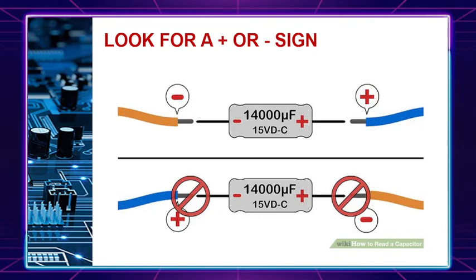placement, it can damage the capacitor or it might explode. If there is no positive sign, you can orient the capacitor either way. Some capacitors use a color bar, usually in a ring shape or barrel shape type, to show polarity. Traditionally, this mark designates the negative end on an aluminum electrolytic capacitor, which are usually shaped like tin cans.